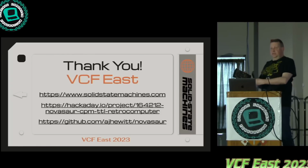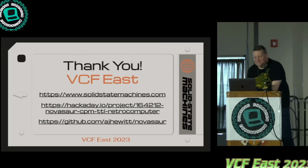I'm thinking about doing a surface mount version, but I want to take it to another level where I can break all this down into single discrete gates, using these little SOT23 packages. It would have about 350 of those, and it could theoretically work. So maybe at the end of the year I'll start looking at that. But I think that's it.